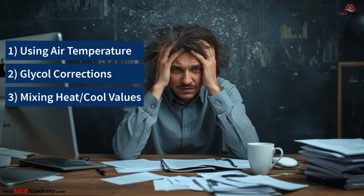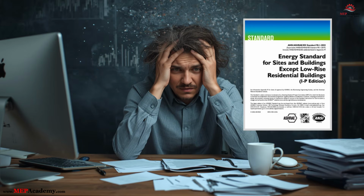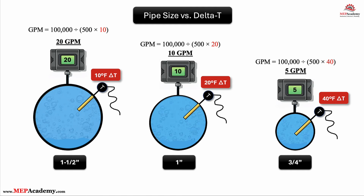Many existing cooling coils were designed around about 10 degrees Fahrenheit delta T, but modern high-efficiency designs and ASHRAE 90.1 typically push toward 15 degrees Fahrenheit or higher chilled water delta T. How delta T affects pipe size. Here's the quick example I mentioned in the beginning, and it's an important one.